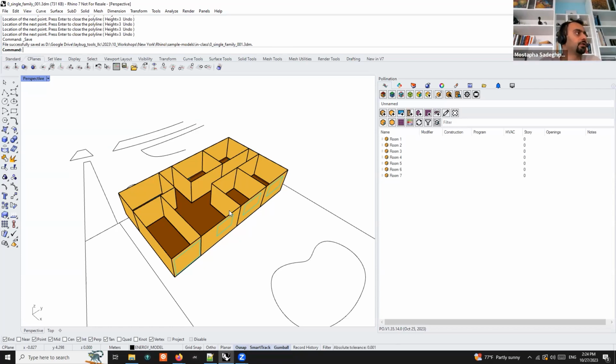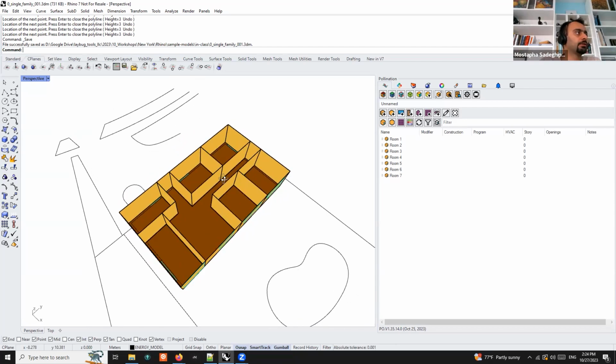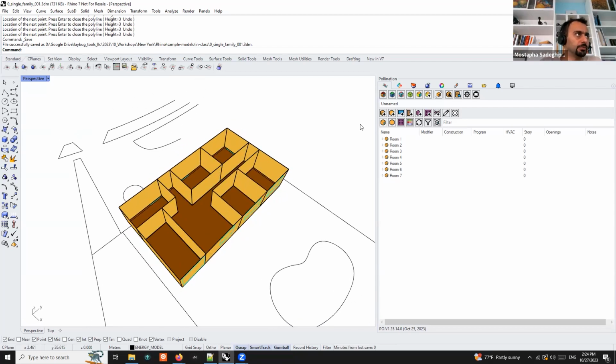Okay, if there are no questions, this was one of the three methods of adding a room. If I click here on plus, there are three ways of adding a room. The one that I just showed you is draw a room. The other one is select geometries, which is the one that I'm going to use next, to use the 3D models that are already in the sample file. And we have another one for select by layers.